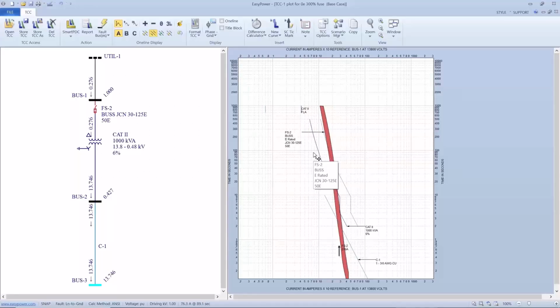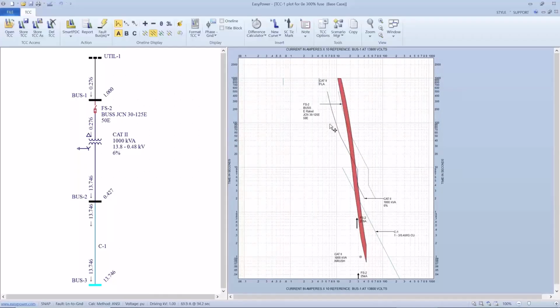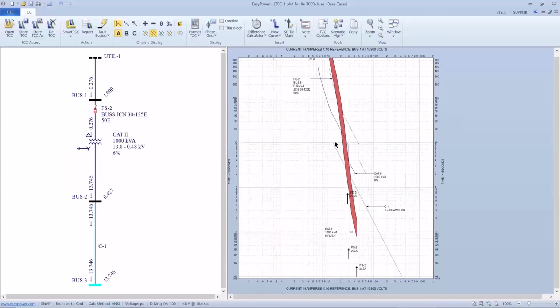So that's one of the reasons that fuses are not that acceptable, or at least have some considerations that you need to make sure your circuit covers this part. Now again, the fuse is in the primary, and so it's doing a not quite adequate job at protecting the transformer from both the single line to ground faults and the frequent fault curves.